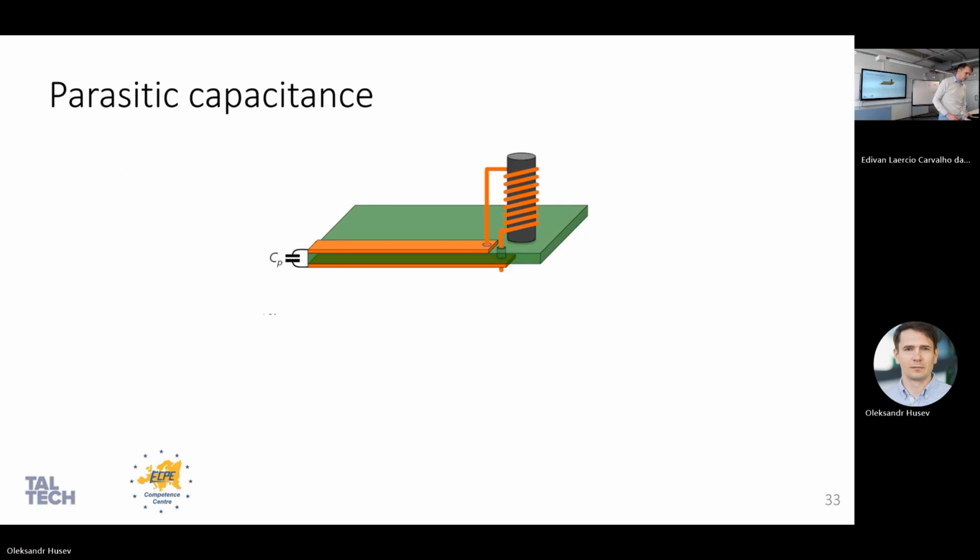So should we use some SMD components and capacitors to compensate? I have never seen any design where you use only an electrolytic capacitor for the switching cell and don't have any film or ceramic capacitor. Because you can't move the electrolytic capacitor, which is the main source of energy, but you can always move small ceramic capacitors and put them as close to your switching cell as possible. And in this case, you always minimize the inductance that is inside the switching cell.